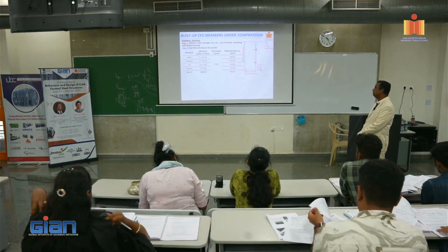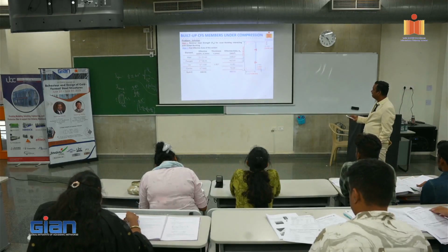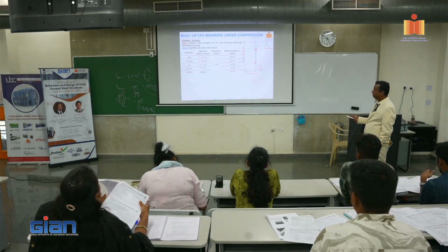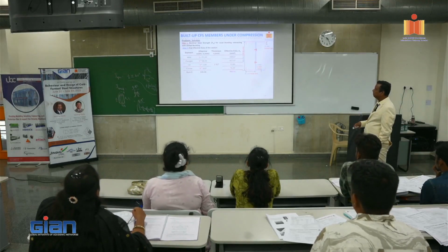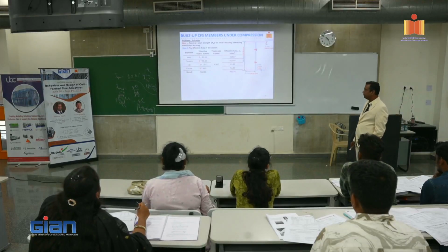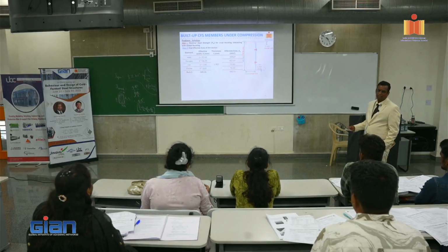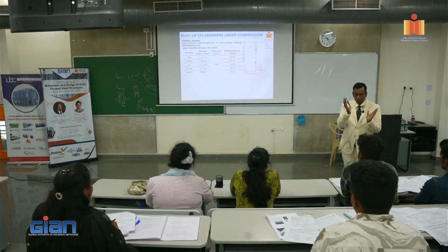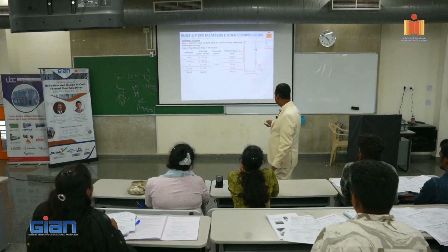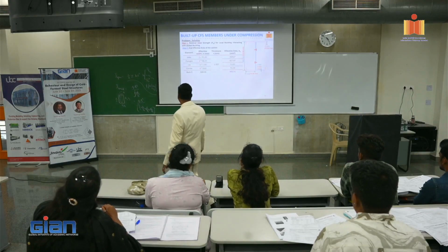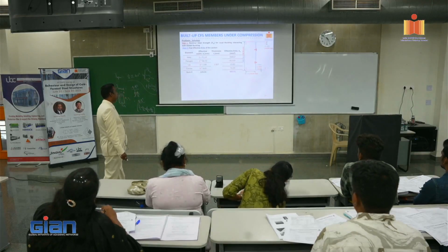So you have this one. Here, how many elements do you have? You have 2 webs, 4 flanges, 4 lips, 8 corners. Corners are fully effective. So the effective width of that is 4.62, right? That you have to do as a circle and 1 quadrant, 1/4 of that. You have done all that stuff, right? So when you do so, you get the summation as 460.36. The thickness is the same. You multiply, you get 900.92, right?